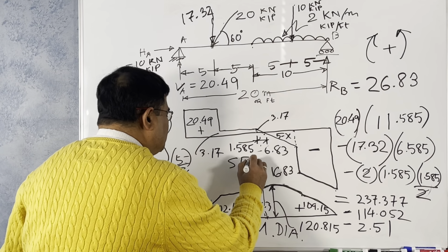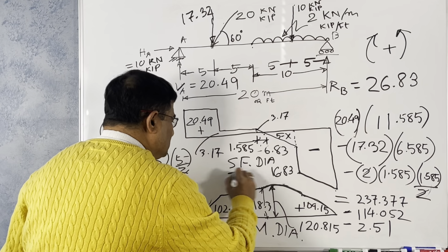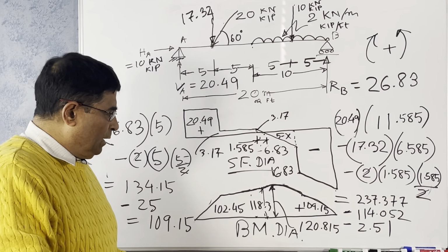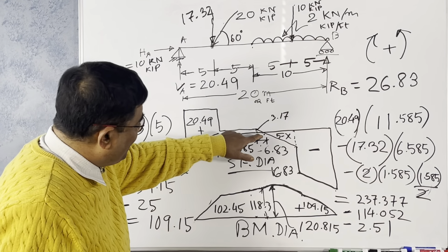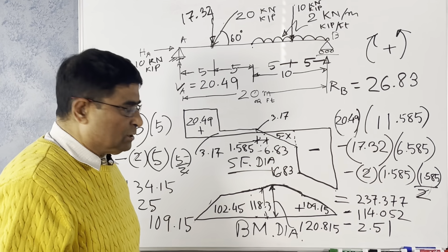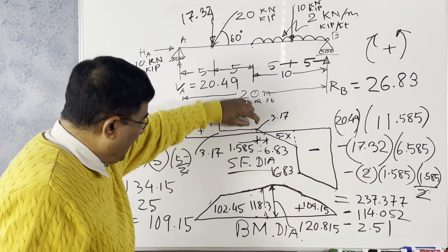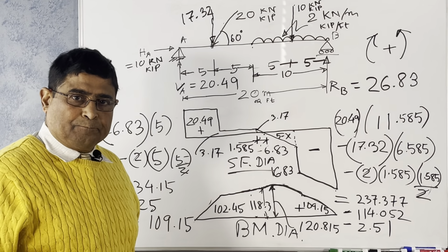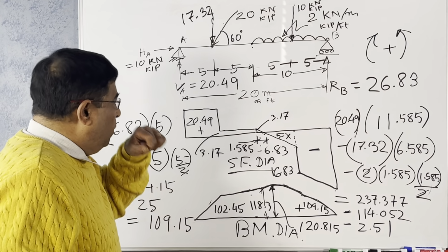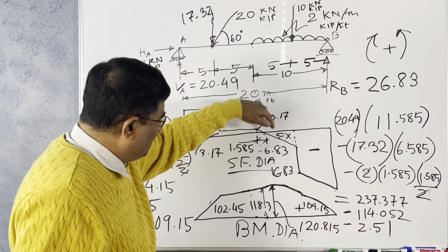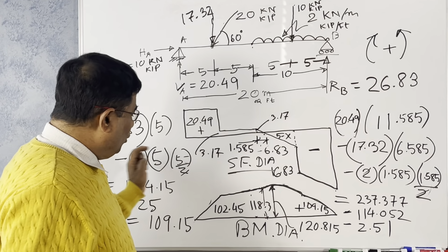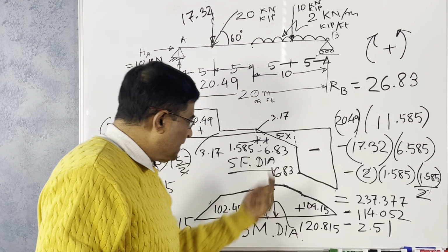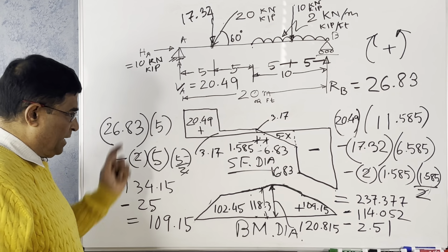This is your shear force diagram. Okay? This is all about it. It's a complex load, but don't get scared. And you know how to calculate the maximum by the similar triangle condition. This is very important. You should know how to find out the x distance. Once you find the x distance, add up the distances and things will be easier. When you see fewer forces on a member, take that side. Don't go all the way from the left. There are more loads on the left side, but fewer loads on the right side. It's easier to calculate the moment from the right side.